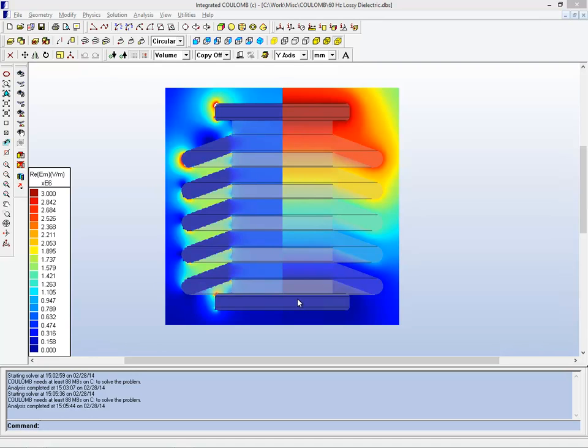And again, referring back to the formula page that we looked at, you can think of this in terms of current flow. There is a current flowing, and it's the conductive current that's dominating in order to change this from the permittivity answer. So there is a current flowing down the middle, and there is a pretty close to uniform electric field down the middle associated with that current flow. There is no current flow out in the sheds, and therefore each shed maintains pretty close to the same voltage as the material right beside it where the current actually is flowing.